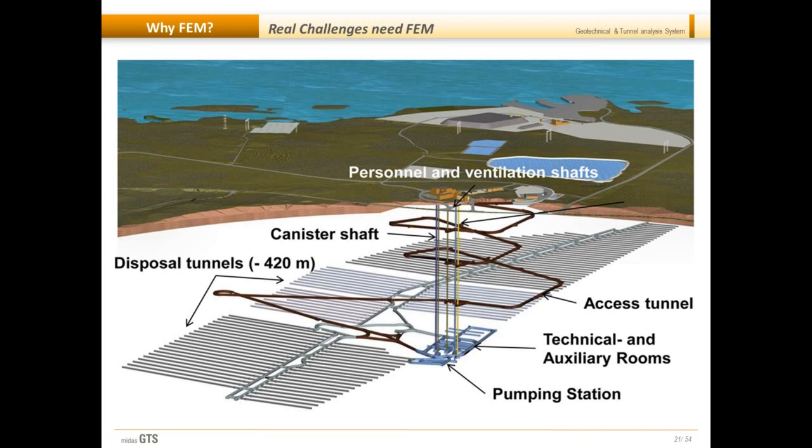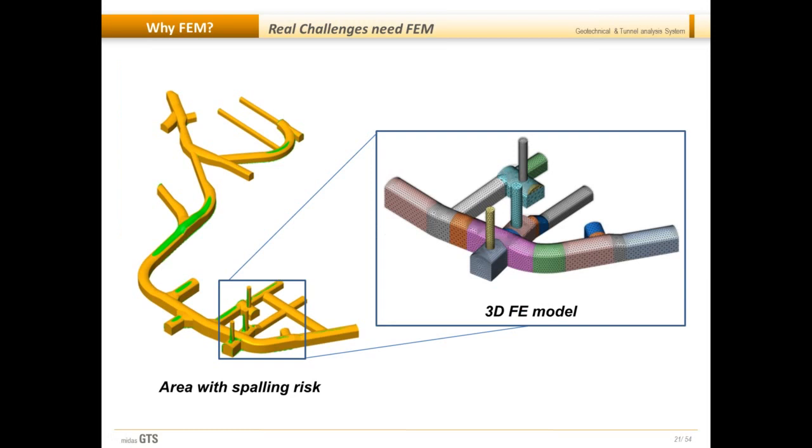Then this is an example from a nuclear power plant disposal site, and you can see this tunnel alignment is going pretty deep into the soil strata, and you can see that with these tunnel alignments at such greater depth, you have to analyze what different types of soil layers you would be intercepting. This type of analysis could be done, and you can then find out that, okay, these are the regions where there is a risk of spalling, and they are the soft strata.